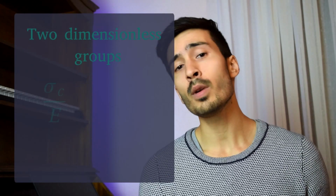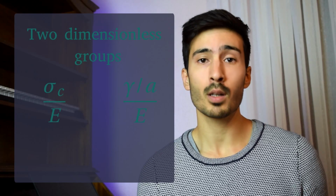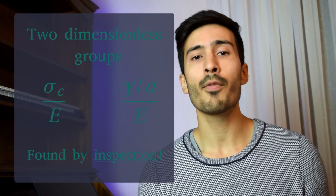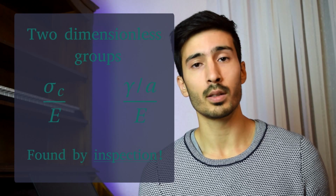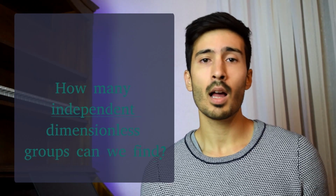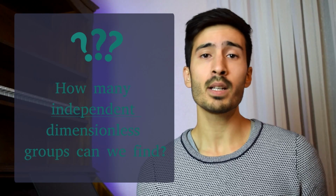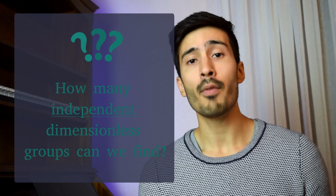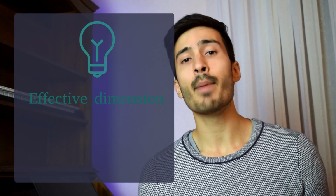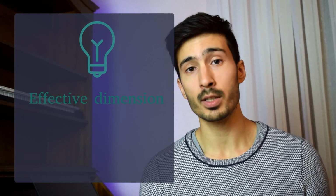Before we proceed, maybe it is a good idea to formalize a bit what we did. We found two independent dimensionless quantities or groups by what's called inspection, meaning we found our two dimensionless quantities just by looking at their dimensions and thinking a bit. In general, how many independent groups can we find? To answer this question, we must first introduce the idea of an effective dimension. Getting back to our example, our two effective dimensions are force and length.